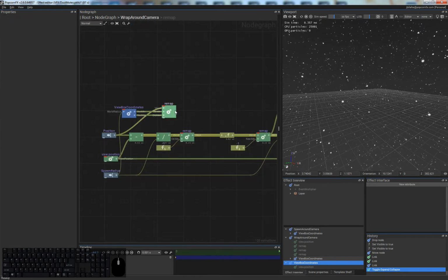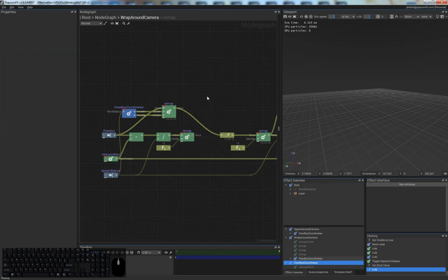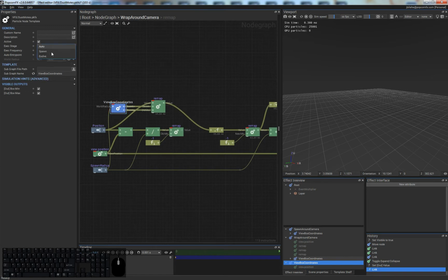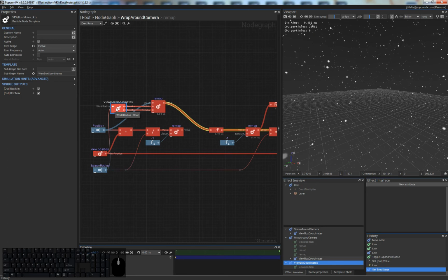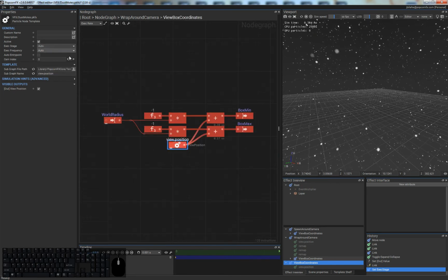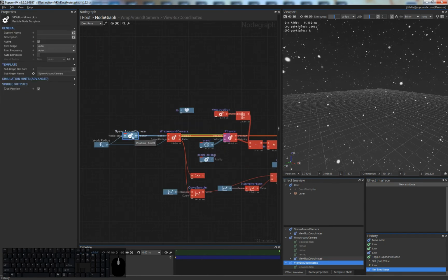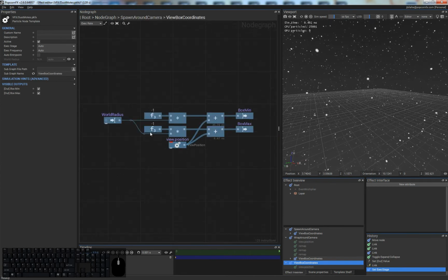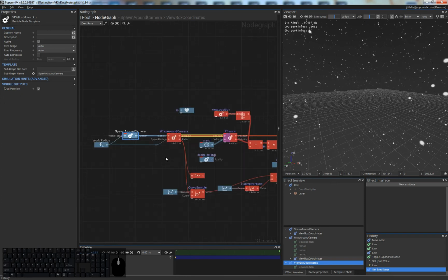So by doing this, I can actually bypass all these nodes and directly wire this into the frac. And this doesn't work because I need to set this to evolve. Here my view position was at evolve. And so I need to tell this node to run at evolve as well, because it has a view position which is in auto mode, so by default at spawn. And this is actually what we want, because otherwise at spawn this will turn this node into evolve if we had set the view position at evolve. So we keep all this to auto, and we say on the node itself when we use it whether we want it at spawn or evolve.